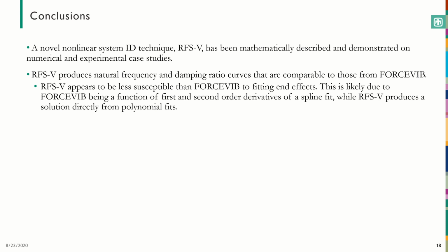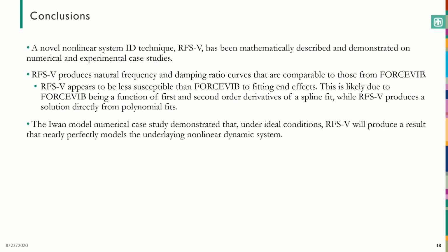This is probably because force filter depends on the first and second derivatives of a polynomial fit, whereas RFSV just operates directly on a polynomial fit. The numerical case study, where I simulated the response of a modal model to a sine beat, showed that with ideal data, RFSV essentially perfectly models the underlying nonlinear system.